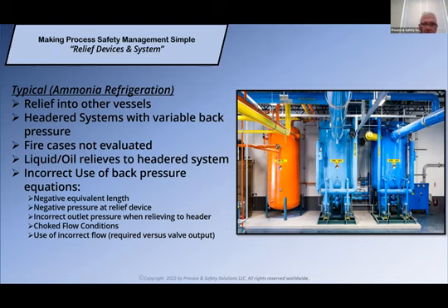So making sure you evaluate fire cases and what's going to be relieving at the same time so that you make sure you're taking into account any back pressure situations. Liquid or oil relieves to the headered system. Well, I shouldn't have to explain the reasons why for this.